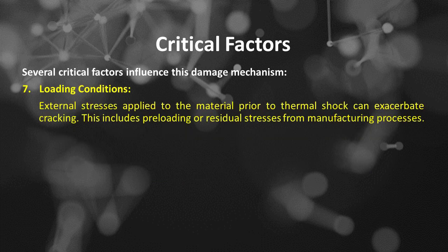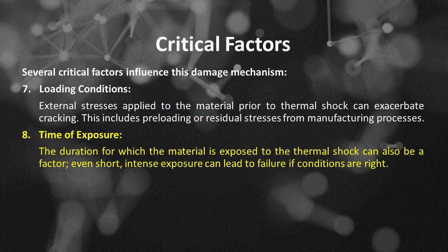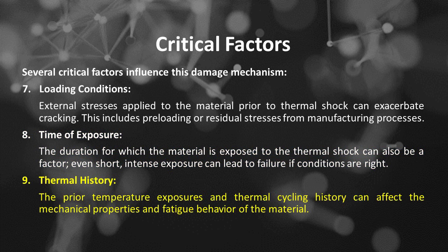Number 7 is loading conditions. External stresses applied to the material prior to thermal shock can exacerbate cracking. This includes preloading or residual stresses from manufacturing processes. Number 8 is time of exposure. The duration for which the material is exposed to the thermal shock can also be a factor. Even short, intense exposure can lead to failure if conditions are right. Number 9 is thermal history. The prior temperature exposures and thermal cycling history can affect the mechanical properties and fatigue behavior of the material.